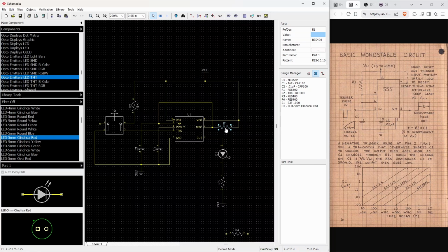It's not exactly 10 seconds, but if we wanted the exact number, we can use the formula instead of the chart. Capacitors generally are harder to find in really specific numbers. So we probably want to keep 1 uF and then find a resistor that matches the formula if we were going to do that. R1 is going to be 10 mega ohms, so I will change that here.